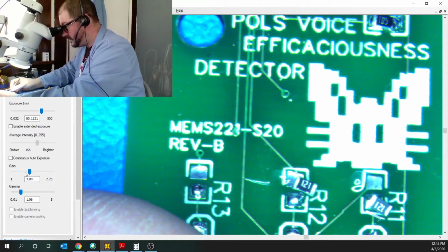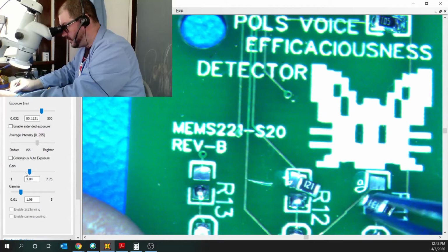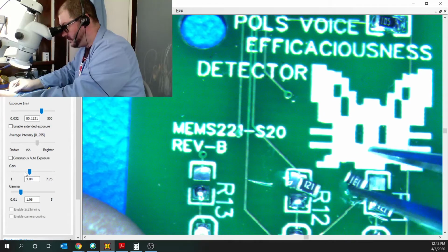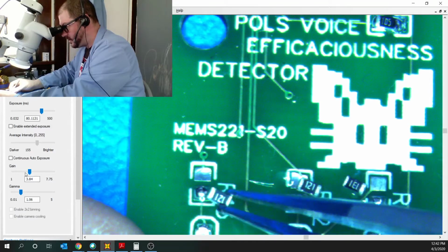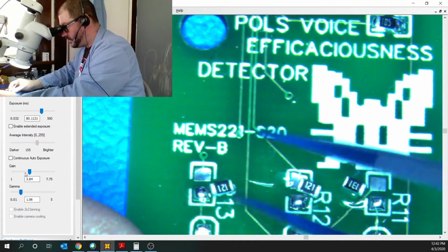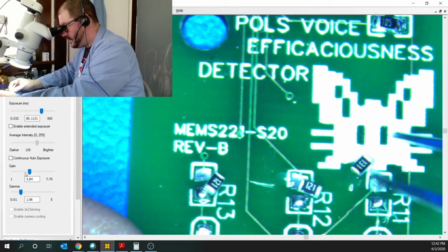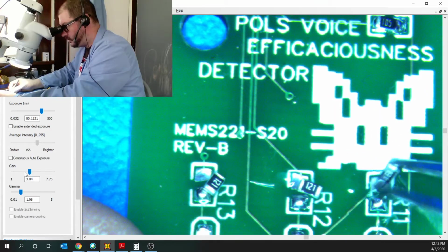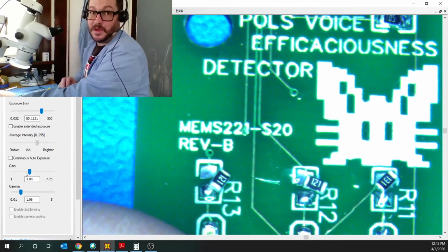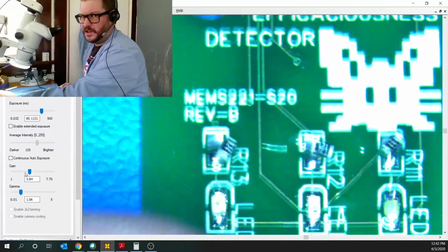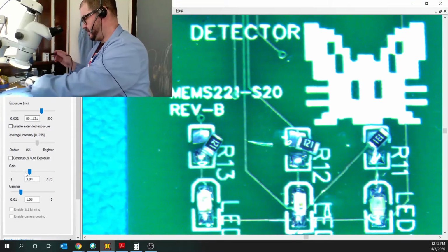So actually I'm not so certain. That one says 131. So it's a little bit off. That one's 130 ohms, while the other two are 120 ohms. That's okay. We'll still work with you in the same way here. So 121, 121, and the red one, the one for the loud noises, or the orange one really, will get 131. All that means is that the orange one will be just a little bit more dim than all the rest of them will.